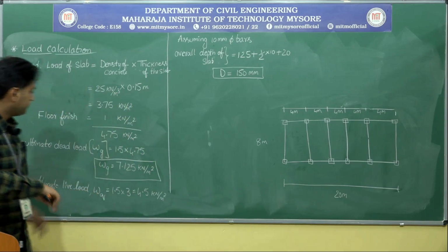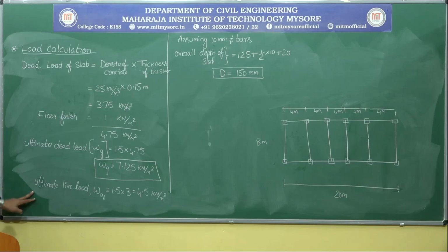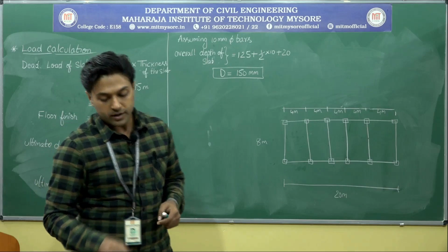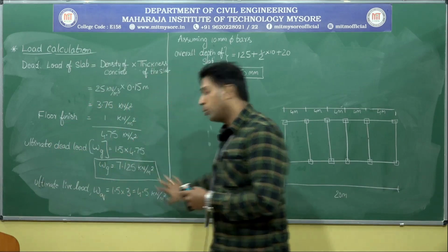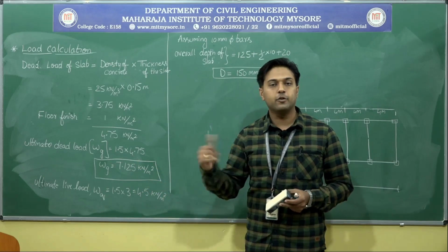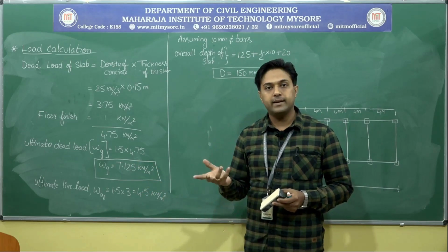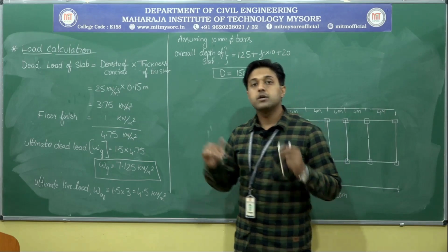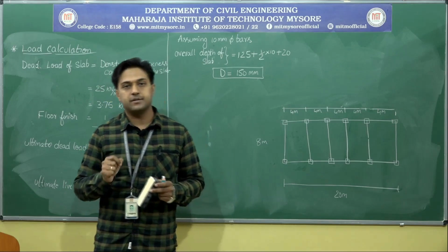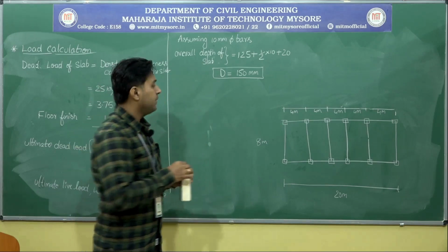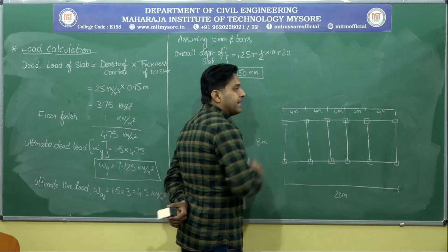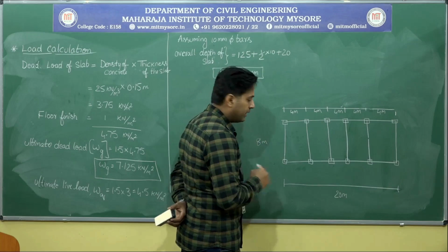Any doubts still here? Any doubts? Now I will be going further. I have calculated the loads. So what are all the loads that are coming on the structure? Soon after calculation of load, what I need to do is calculate the bending moment. Now we'll go with page 12 of IS 456. There they have given some values. Observe here. I will be giving you an idea how I will be taking the bending moment.